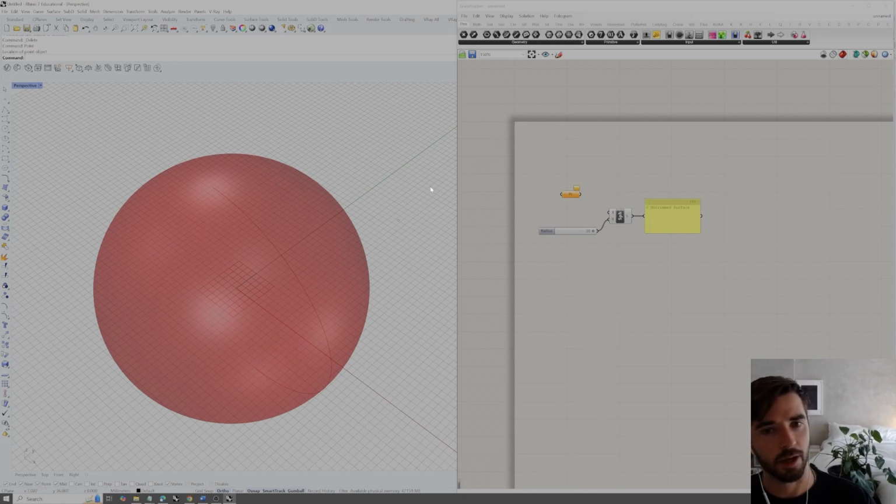So first I'm going to left click and drag over my point, and then we need to hover over the point, right click on this point parameter inside of Grasshopper, and we can see that there are some options for setting one point or setting multiple points. So I'm going to just go ahead and select set one point. And with that point selected, it automatically updates this point and now says referenced point. That's because it's referencing the point that exists inside of Rhino.